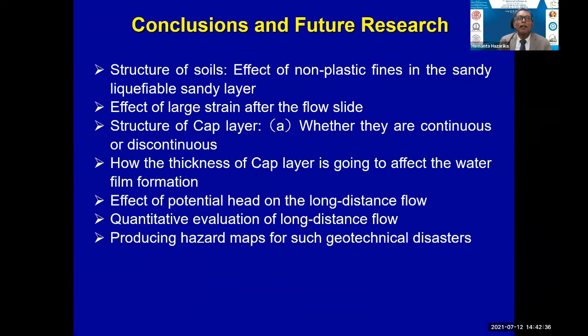So my final conclusion is that we still could not arrive at any definite conclusions because this is a very complicated phenomenon. So we have to look at the structure of the soil, the effect of the non-plastic fines in the sandy, liquefiable sandy layers, and the effect of the large strain, because after the flow, they're moving at a very fast velocity. So that is a large strain phenomenon. So we have to decouple it from the pure dynamic phenomena before and during the earthquake.